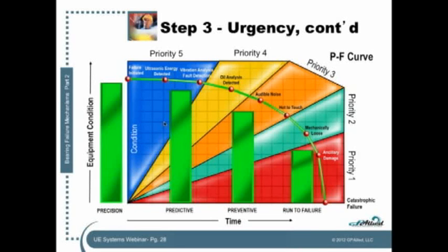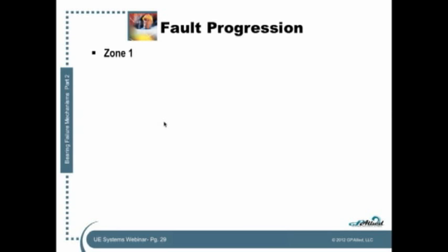So this slide actually is one of my favorites, because as the signals change from the bearing, we get a pretty nice indicator of what the work order priority needs to be when we put that work order in the system. And we can think of it like this. In zone 1, ultrasound is a very nice tool to find the bearing defect. And we know from the ultrasound that it's still fairly clean noise, it's just louder. And that's that subsurface fatigue screaming at us, saying, hey, remember, it's high pressure, small movements, which makes super high frequency noise, right? But it's clean noise. So the bearing sounds clean, but it's just louder, so it's telling us something.